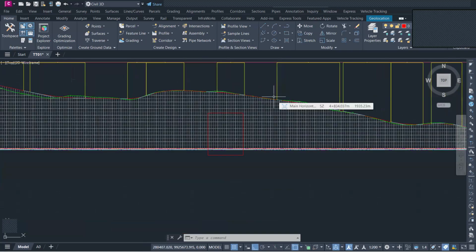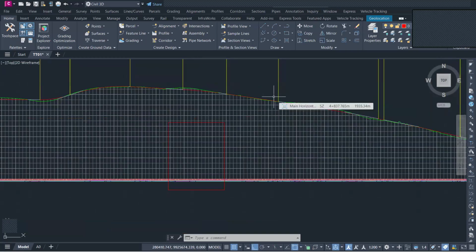You also need them if, for example, you are in an embankment and the left-hand side doesn't have an outfall, so you can provide a culvert that is just meant to shift water from this side to the other side of the road. Again, the drainage of the area, mostly the terrain, informs you. So you make your judgment and say, I want to channel this water from the left-hand side to the right-hand side. Okay.